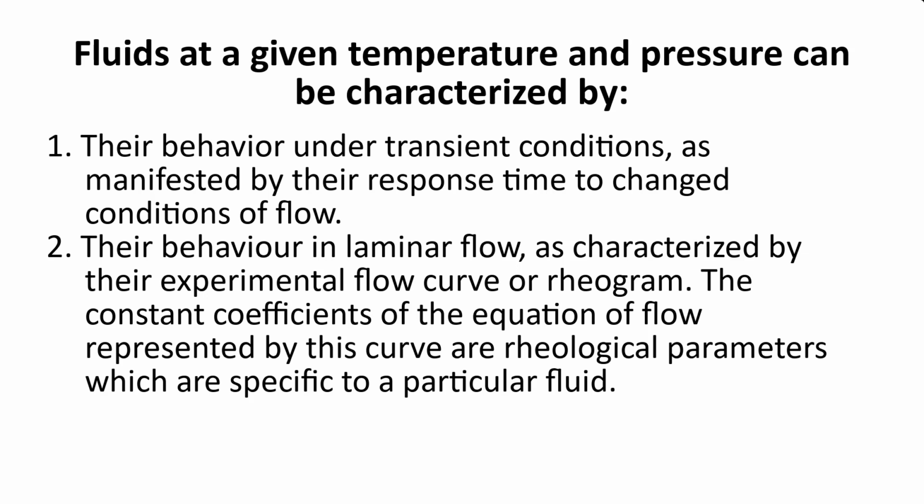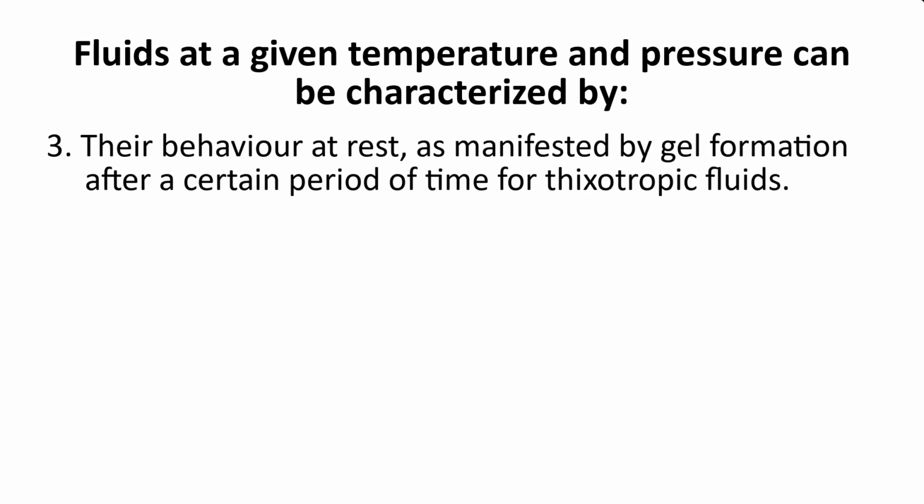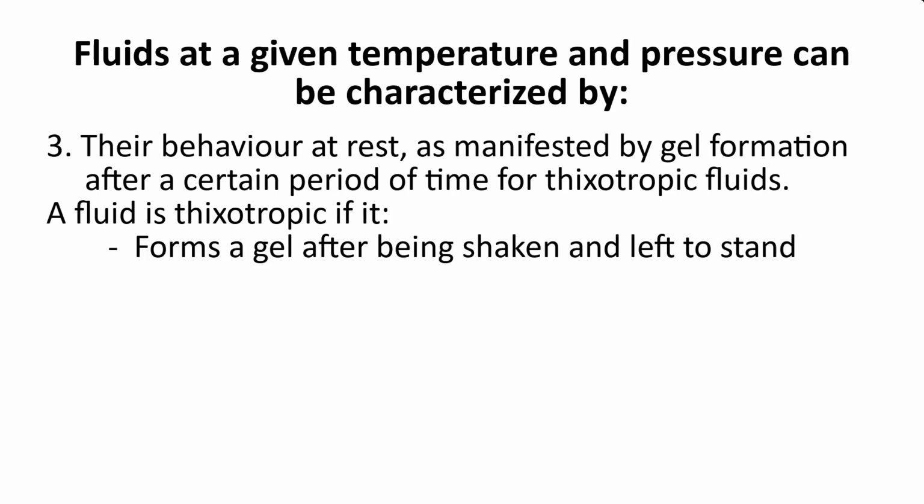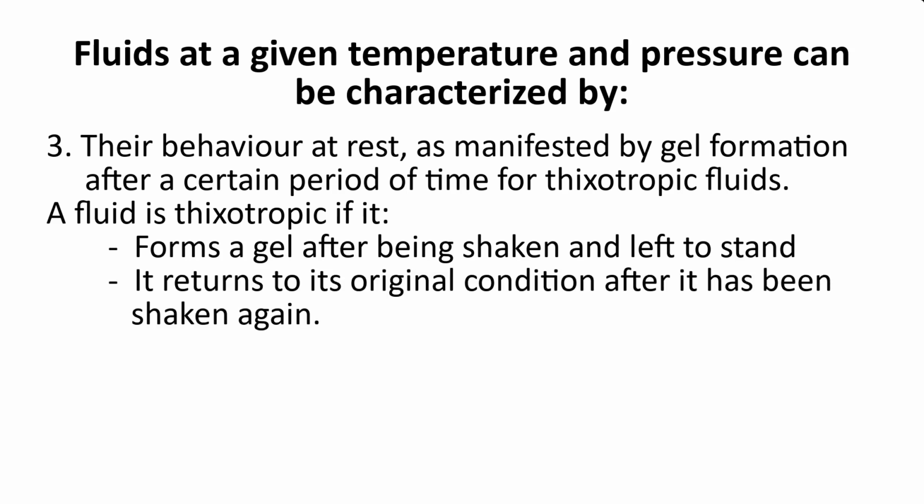rheogram. The constant coefficients of the equation of flow represented by this curve are rheological parameters, which are specific to a particular fluid. Their behavior at rest is manifested by gel formation after a certain period of time for a thixotropic fluid. A fluid is thixotropic if it forms a gel after being shaken and left to stand. It returns to its original condition after it has been shaken again.